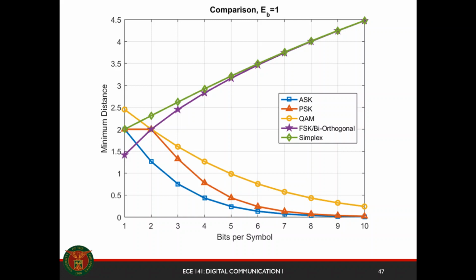If we recall from FSK, a frequency band of M delta f defines the FSK signal. However, if we want to have more symbols for our constellation, we need to increase the bandwidth. Even if the power is limited, that's fine. We just increase the bandwidth, we get more symbols. Turns out that if we increase the symbols more, then we create a signaling system that is more reliable each time. Downside is we just spend more bandwidth.